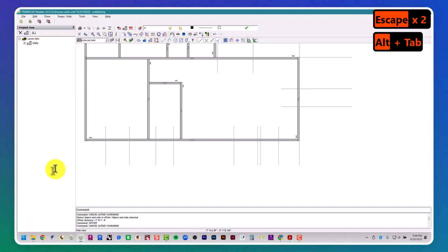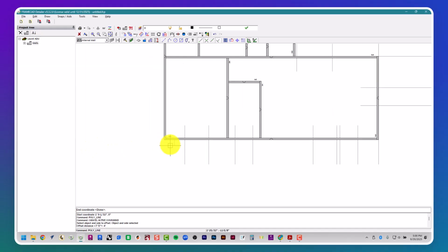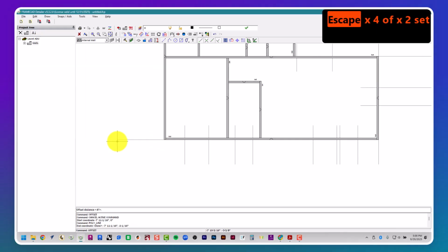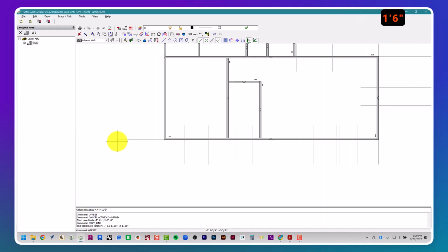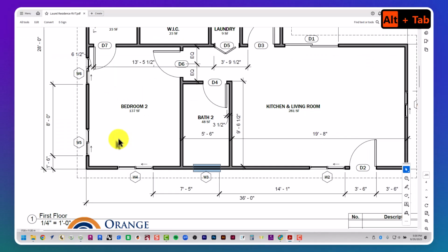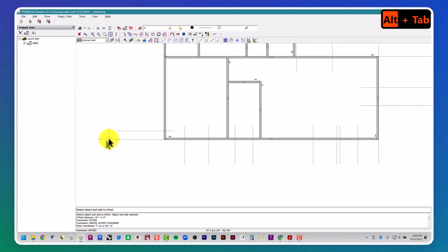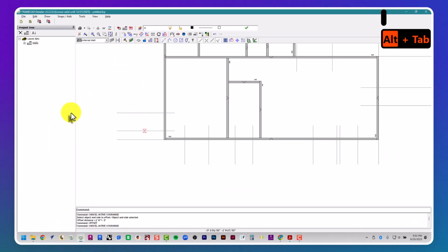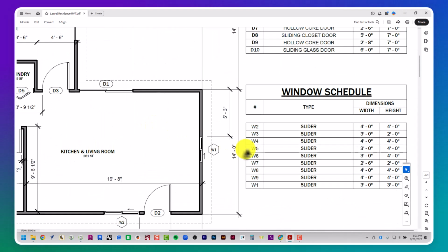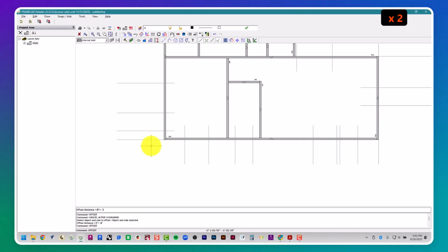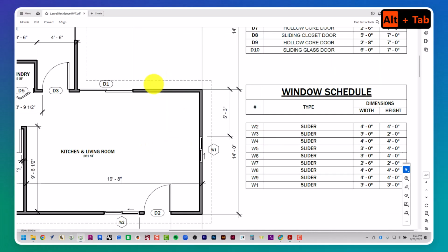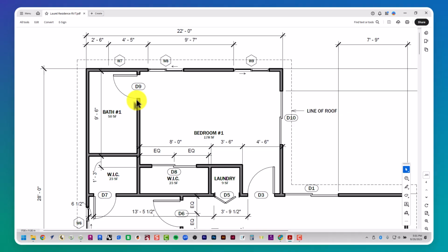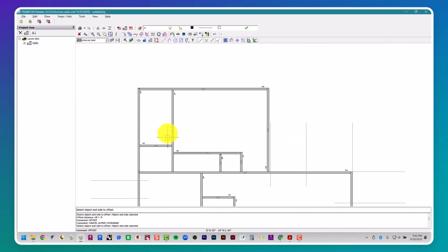Let's draw another line. Let's do a polyline from here, there, and then offset a distance of 1'6" upwards. And then that window's W5. It is 3 feet wide. Let's do 3 feet. Okay, and then I have another opening 8 feet away. And then that one is W6, which is also 3 feet. All right, any other openings on that side? Nope. All right, let's navigate up here.